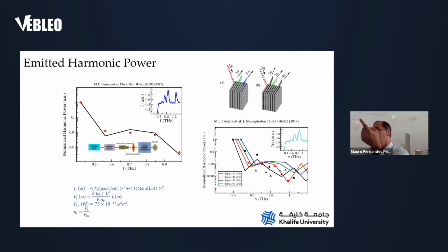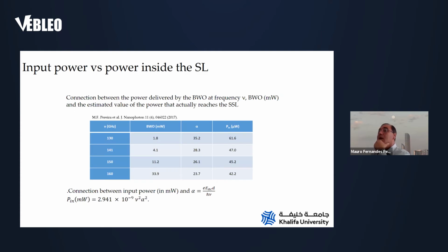So basically the electrons are oscillating, and what we have is a modulated Bloch oscillation. Okay, this is the underlying physical mechanism for this emission. Unfortunately, you have to put a superlattice in a specific waveguide, so you can inject, for example, GHz radiation, inject it with an antenna, and the oscillating gigahertz current goes through the superlattice and harmonics are emitted. When you do this, a lot of power gets lost.